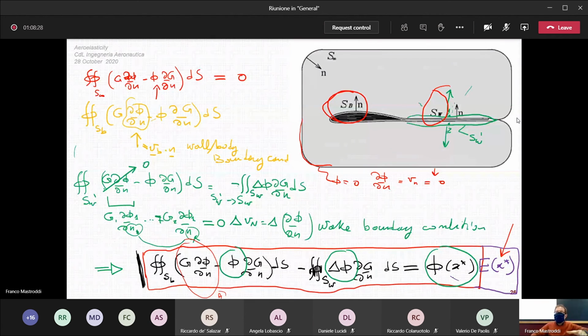So you have to sum the contribution of the panel plus the contribution of the other panel. You have a summation. The summation is exactly the corresponding discretized quantity of the integral. But you have supposed that the phi on the n is constant in the panel, and so you put this quantity out of the integral, and name this like k key.